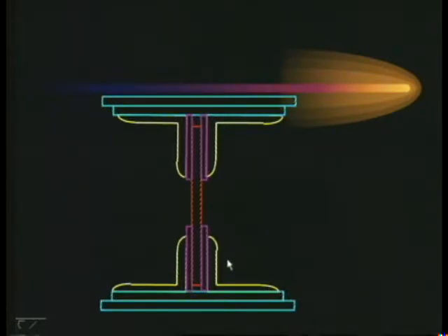And the sections can be riveted. You can have a rivet here, one rivet on this. That means rivets connecting the flange angles to the web plate, and flange angles to the flange plates. So these designs you can learn later on, and at this point let me tell you something more about the flange plate also. These flange plates can be curtailed. Curtailed means they can be cut down.